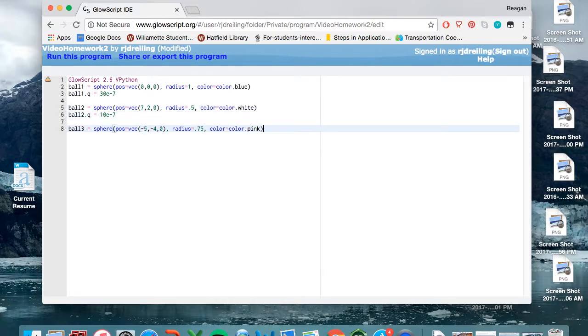Next, because we are calculating the electric field, I'm going to define Coulomb's law constant as Kc. Also, I will define a small scaling factor, SCF, as 0.002, so that the arrows I will put in the field won't look like a mess. Now, I will define a for loop, which will be able to produce iterations of electric field vectors at each point in my domain and range.